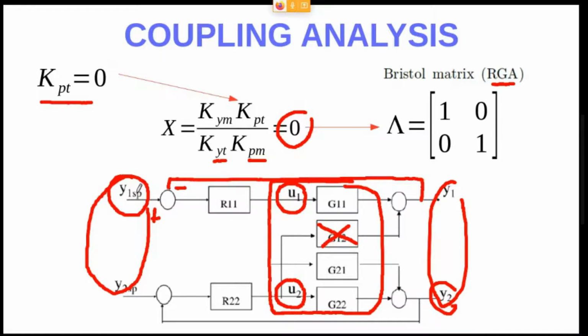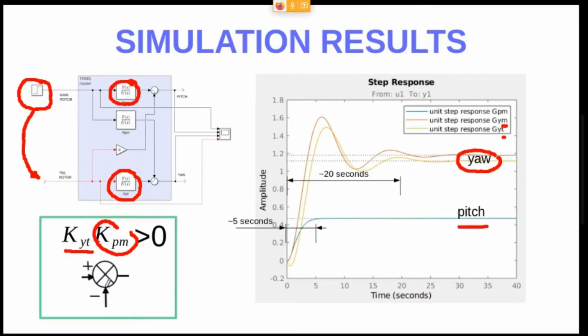The set point will be input as a positive signal, while the feedback is a negative signal, right? This is very important because this means that the error will be calculated in a reverse action of the controller, because both gains here and here are positive.